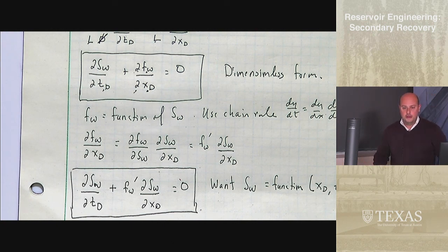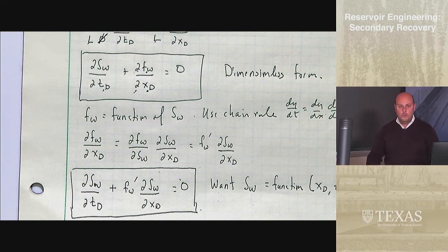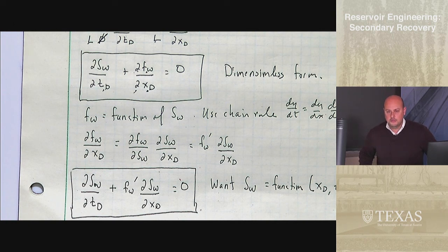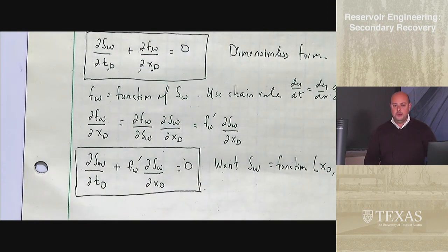If you knew as a reservoir engineer what the water saturation was at all locations and at all future times, you could make some really great decisions, right? You could really impress your boss by saying, we're going to go drill a well over here. We're going to do some sort of stimulation over here. We're going to abandon the reservoir at this time because the water saturation is so high, things like that. So you want the water saturation as a function of space and time. And solving this PDE will give us that.